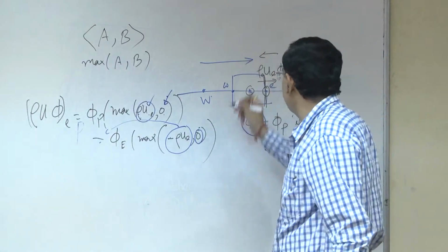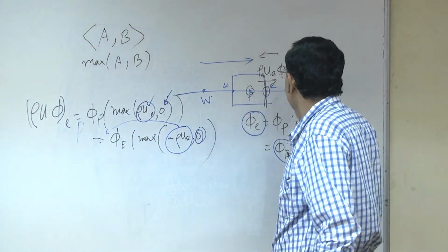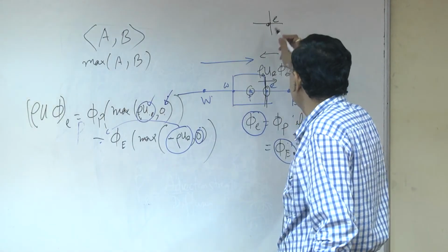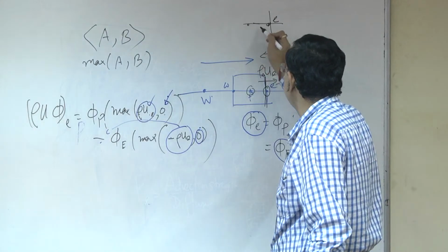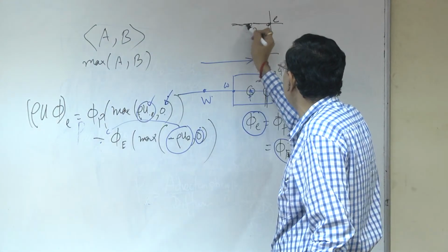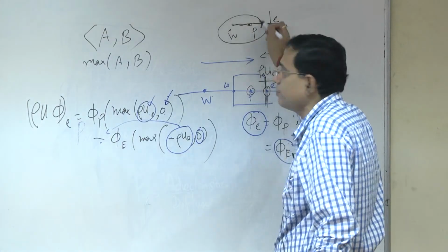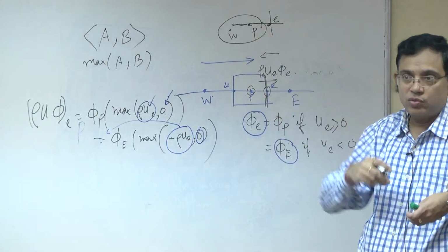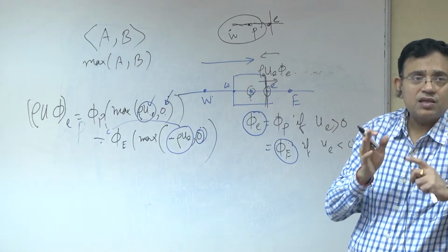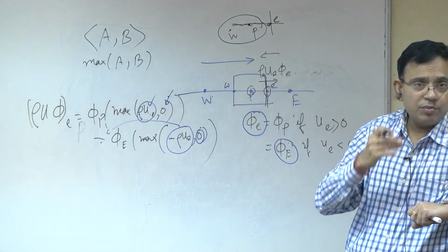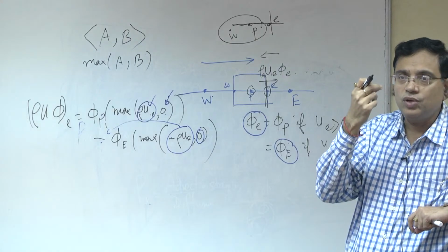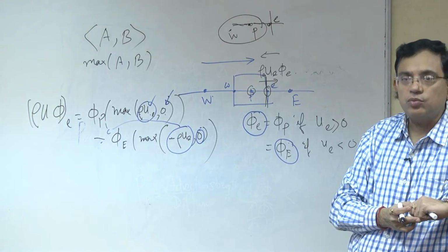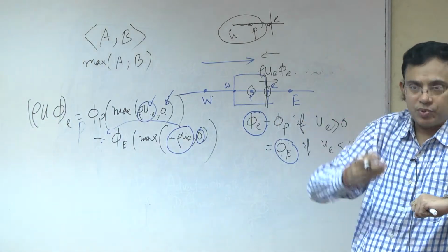Someone may take, for example, say you have this point E. So, the value at E, someone may take that it is influenced by not just P, but maybe also by W, because that will represent more effect of the upwind grids. But if you take 2 points, it will become a quadratic. See, this is like basic maths of interpolation. So, the more points you take, the more unknown coefficients you have. And more unknown coefficients can be accommodated only by higher and higher order polynomials.